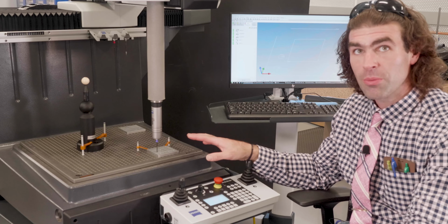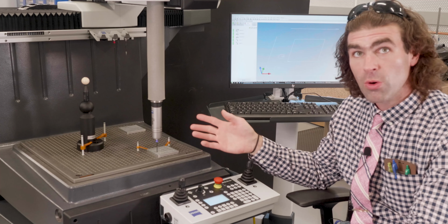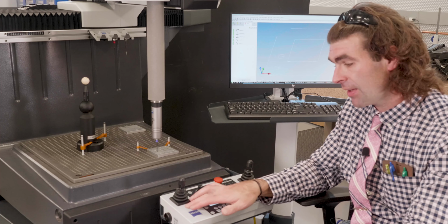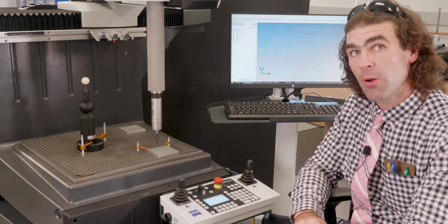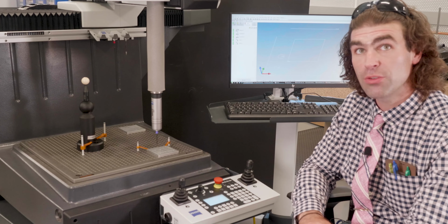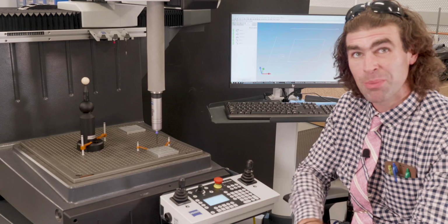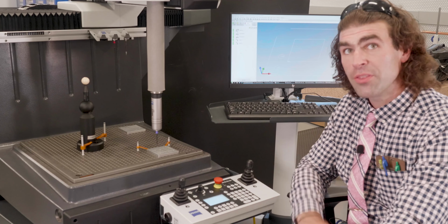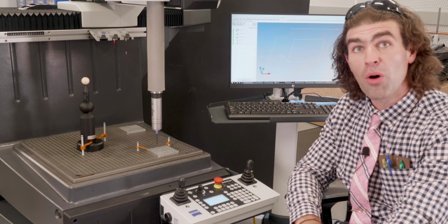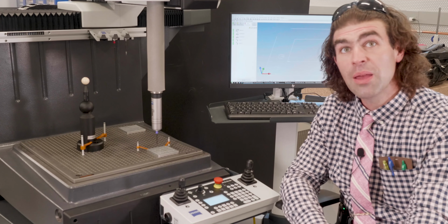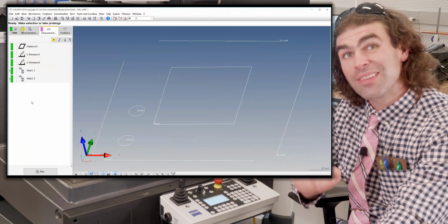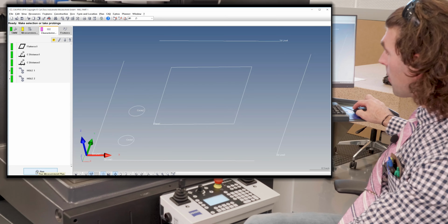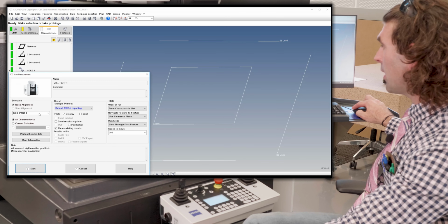You can scan or you can probe the 4 points, or use the 4-point macro. Remember, when the 4-point macro is done, to take the probe out of the hole. I mean, you still have to drive it to the center of a hole, but it can be kind of a time saver. So now we've got everything on the drawing. I'm not going to go through all 14 holes, but I will show you how the program is going to run.